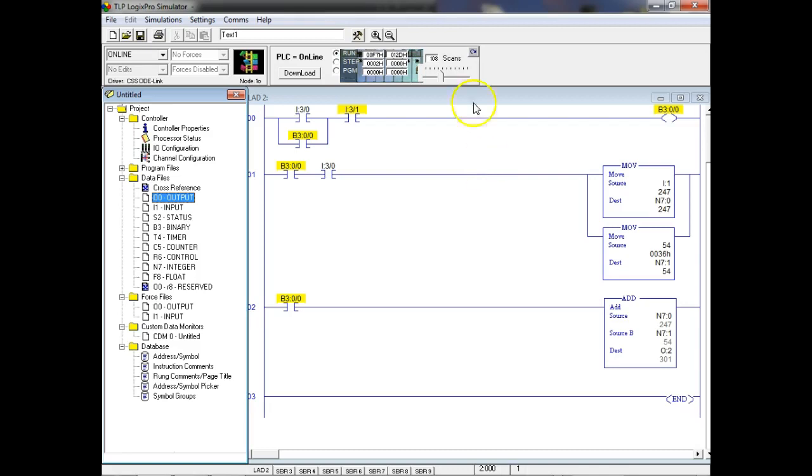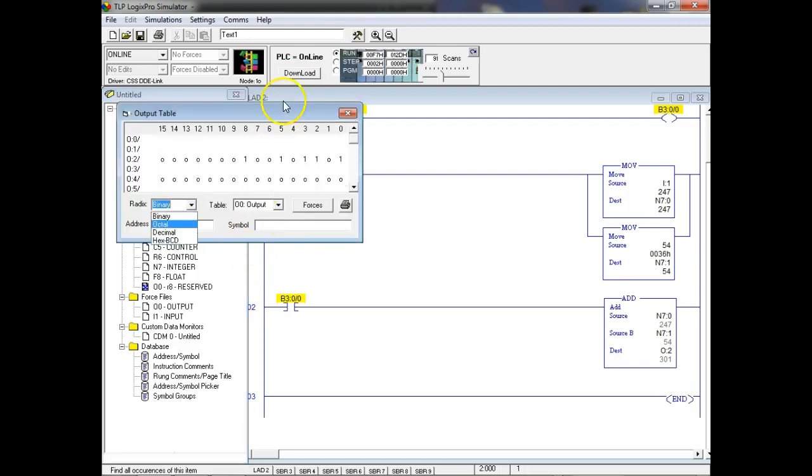If it was an output port, then I would probably want to be in either hex or binary, right? So I know which outputs to expect on, and I wouldn't have to convert it over, right? You understand that? So binary, it would come up and it would tell me exactly which output should be on and which output should be off. This is why by default it goes to binary. Everybody okay?